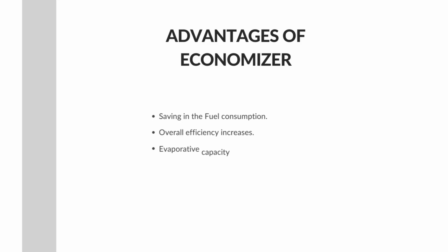Now, let us see the advantages of economizer. The first advantage is saving in the fuel consumption. Second, overall efficiency increases, evaporative capacity of the boiler is increased. Last, protection from chilling of the boiler metal.